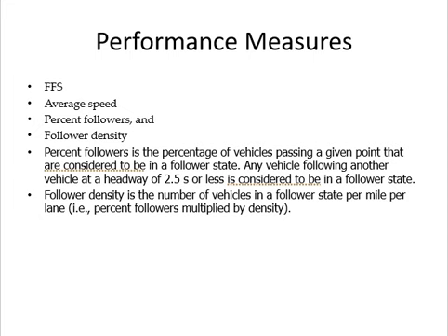If you have 1,000 vehicles in traffic, what percentage of those vehicles are in this condition? This is called percent followers. Out of the total traffic, how many of them have a headway of 2.5 seconds or less? These are called percent followers. Clear? What is density?